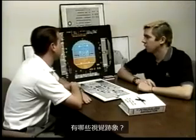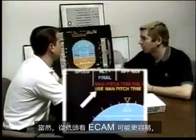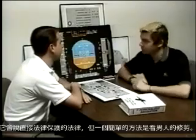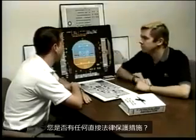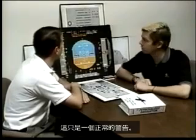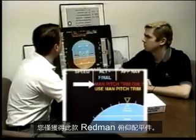What are some visual indications? Easiest one is it's going to come up and say use man pitch trim. Of course, probably even easier to look down at ECAM and it'll say direct law protections lost, but an easy way is to see man pitch trim. And do you have any protections available in direct law? There are no protections. You have VSW, that's not a protection, that's just an all warning. You get this red man pitch trim only.